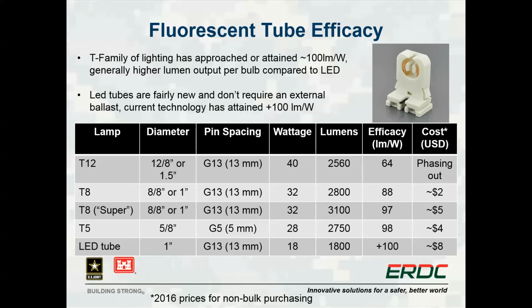Fluorescent tube lamps do require a ballast for the fixture, and the whole fixture will not operate when the ballast fails. This can be an ideal time to replace a fixture with LED lamps, as removal of the ballast would be required in either case.